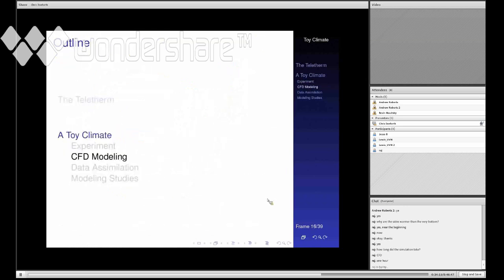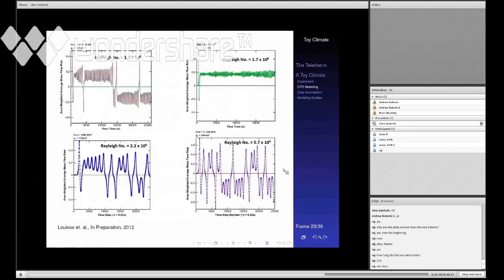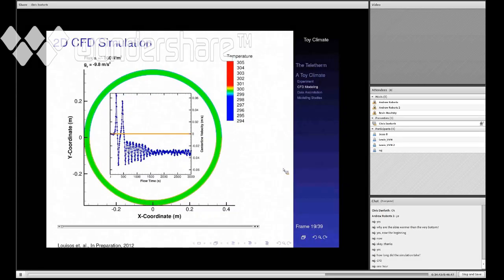The CFD itself, what you're looking at here, is a two-dimensional simulation where we pretend that we have two annuli, so cylinders that go off towards infinity, in towards the screen and out at you, and that simplifies the number of locations you need to pay attention to. We also have simulations fully in 3 dimensions where we actually simulate the full loop, and it's more like 10 million finite elements that we're looking at. So the 2D simulations are quite cheap. Something like what you see here might take an hour on maybe 4 to 8 processors, and this is Fluent. We use Fluent, but we're switching over to OpenFOAM, open source software for CFD.